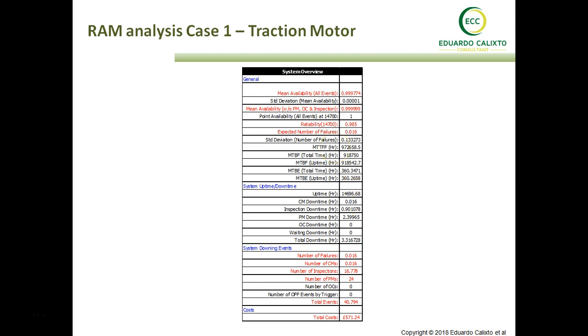And of course, if you have random failure, there's no pattern or tendency of time to have some failure. We need to look at reliability, see when it achieves a lower level, where we have expected number of failures equal to 1, and before this time we implement some inspection and test. So that's why we are highlighting this type of index, and I suggest not using mean time between failure.